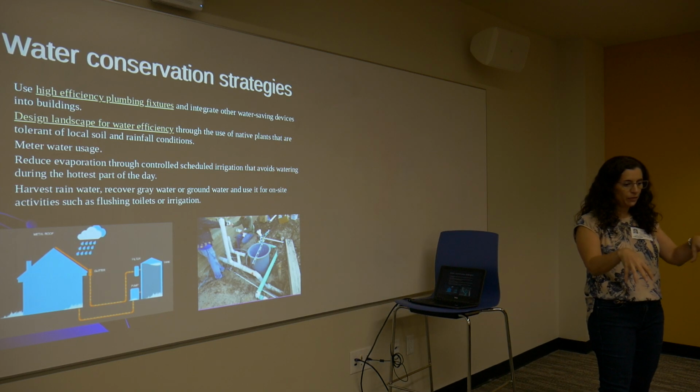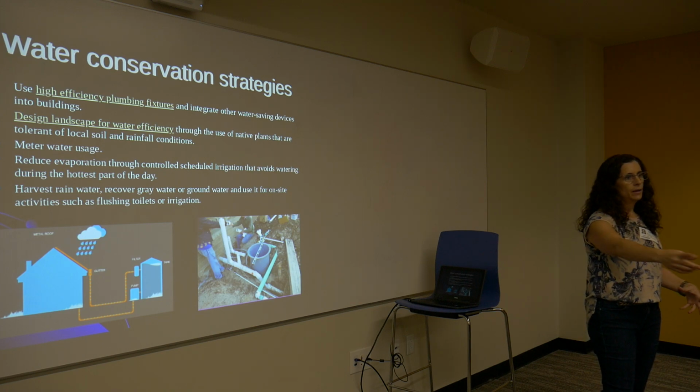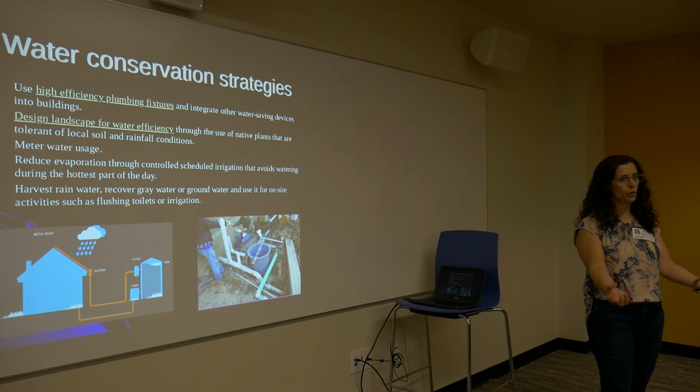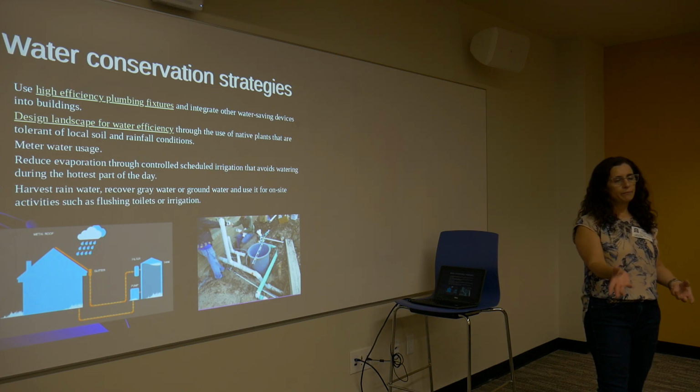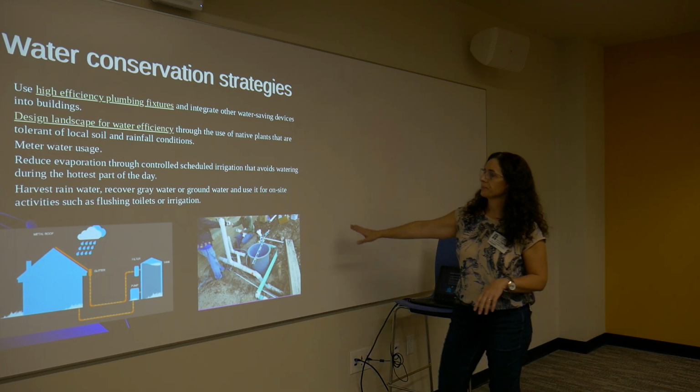And the groundwater as well, when it has already rained. There are systems where, when the rain has already happened and it went through the soil, you can have a system of perforated plumbing, so you can actually absorb that water and take it before filtration to go to a tank like this.